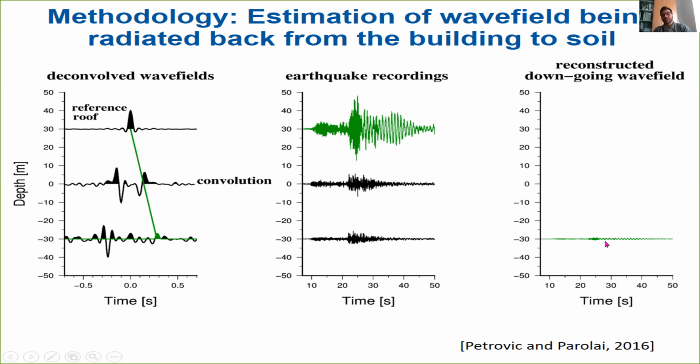You already notice that this wave generated by the building has a very nice oscillation. And this oscillation is nearly at the frequency of resonance of the building. So the building will start oscillating and will induce, it's like a vibroseis, you can see it in this way, a vibration in the ground, in particular at the frequency of the building. And we can recognize this even at 30 or, in some cases, even more meters in the underground.